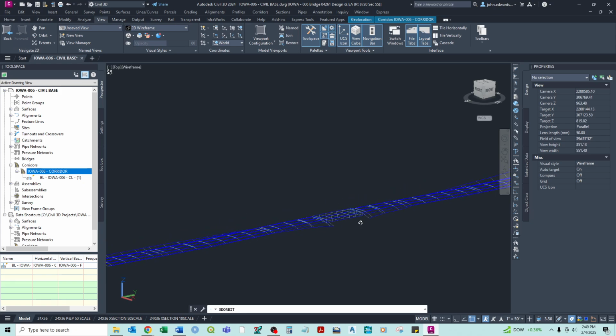of your roadway. Now you'll note something right in here. You see how this end shoots straight down to nothing, or to zero. And this is a good indicator. If you'll recall, we moved that back to match the profile, but that means I didn't type in the exact right number, and so it's going just a little bit past where it has profile information for the elevation, so it immediately just sends it down to zero.